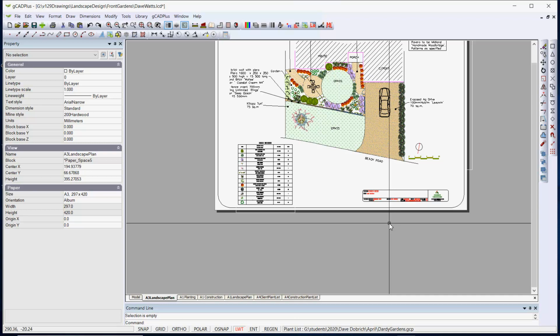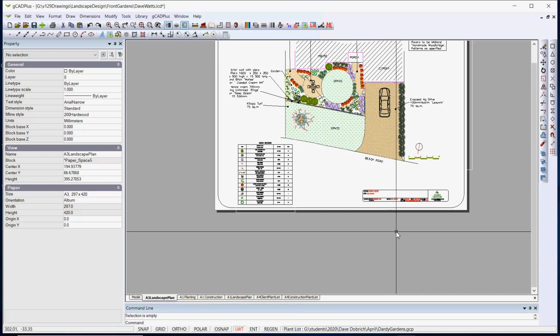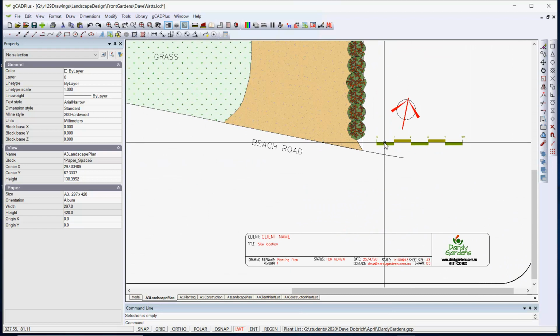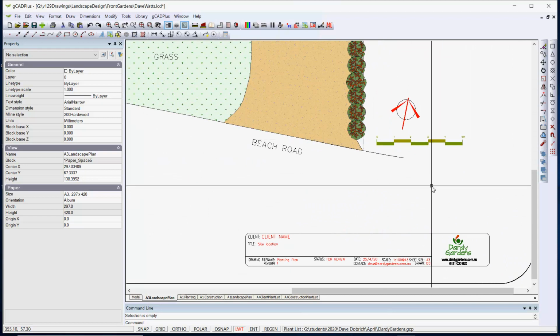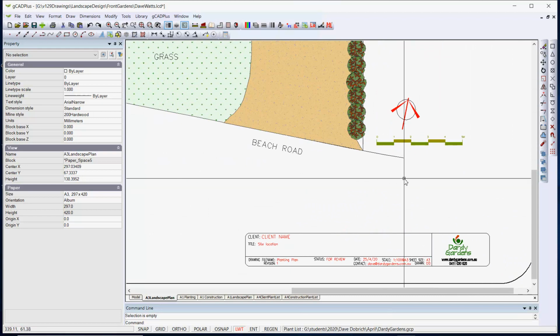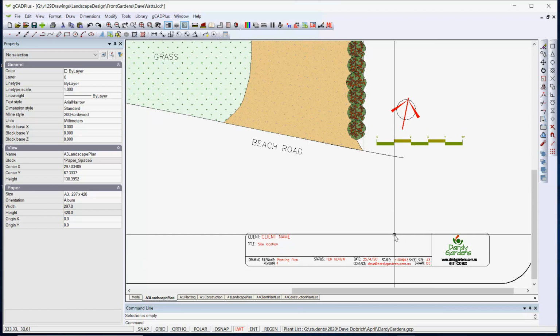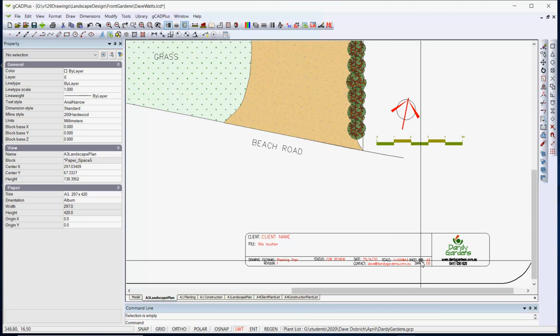That means that the resultant PDF file that we're going to generate here could in fact be printed on any size piece of paper, let's say an A2 sheet, printed off at say a copy center, and if someone's trying to work from it, they'll get accurate values because there's an internal scale here, the north point of course, but the scale says 1 to 100 at an A3 sheet, and sheet sizes mention A3, so clearly if someone picks up an A2 sheet, there's going to be a warning.